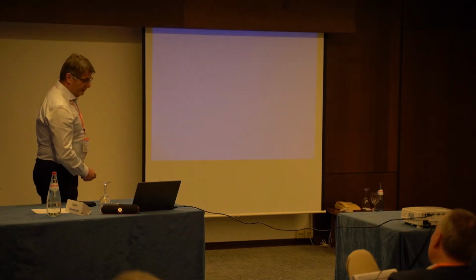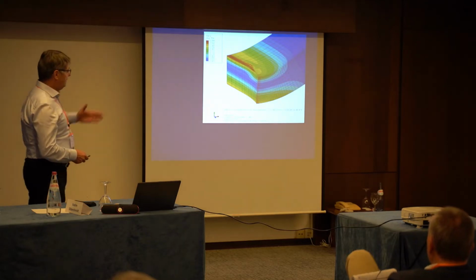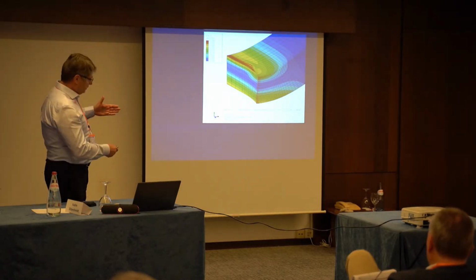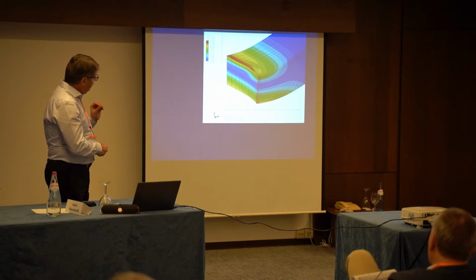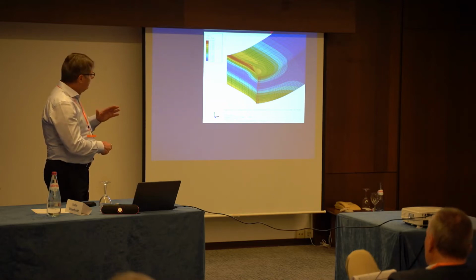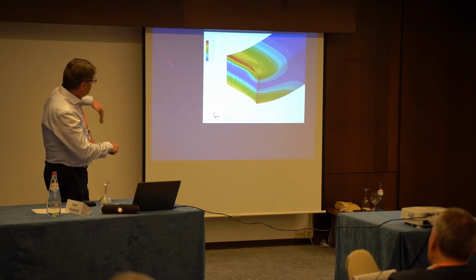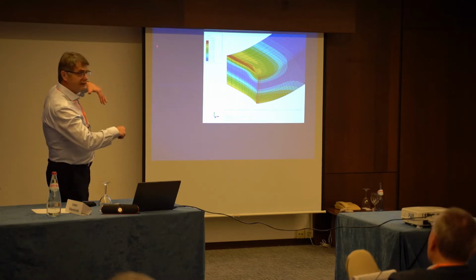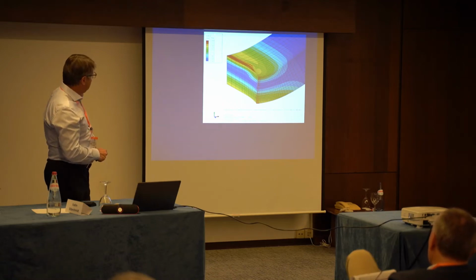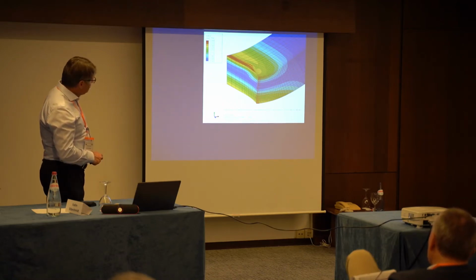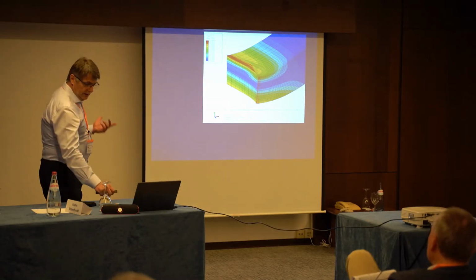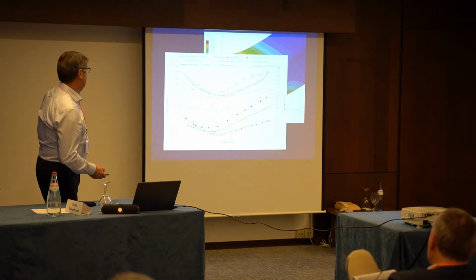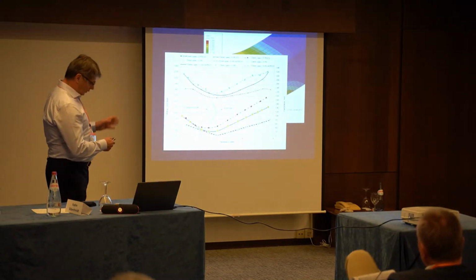So this is now the simulation we did, and now it is only a quarter of the sample. Because in the middle point, here is the middle point, you have the highest stresses, and we only now consider this tip here. This is half of the specimen, and the second half is on the other side. This is actually the bent specimen, and you can see this is the equivalent deformation. In this point it is highest, because in this point we also have the tension of residual stresses.